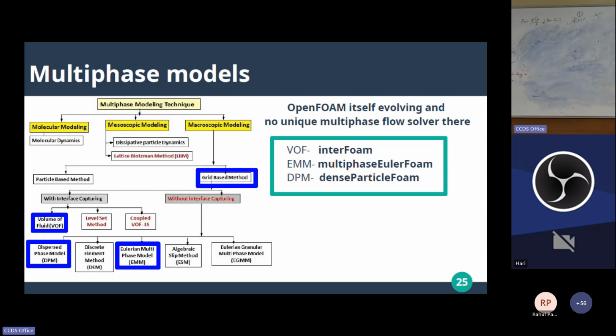So basically in fluid mechanics, whether we say compressible flows, shocks, gas turbines, whatever, the grand strategy is the same. The way it has evolved over time, people always construct meshes and apply certain conservation principles like mass, momentum and energy conservation, and write partial differential equations which vary with time and space for the velocity field, maybe density, maybe temperature, a field description.